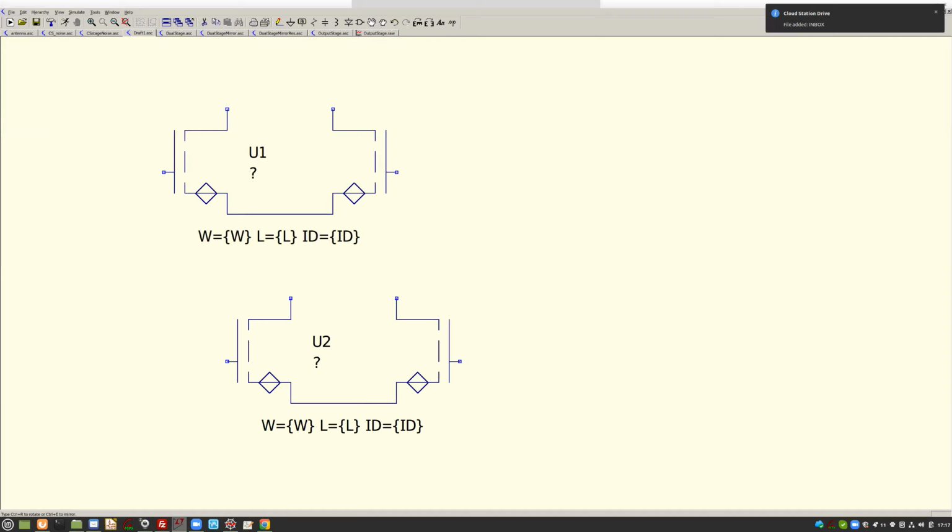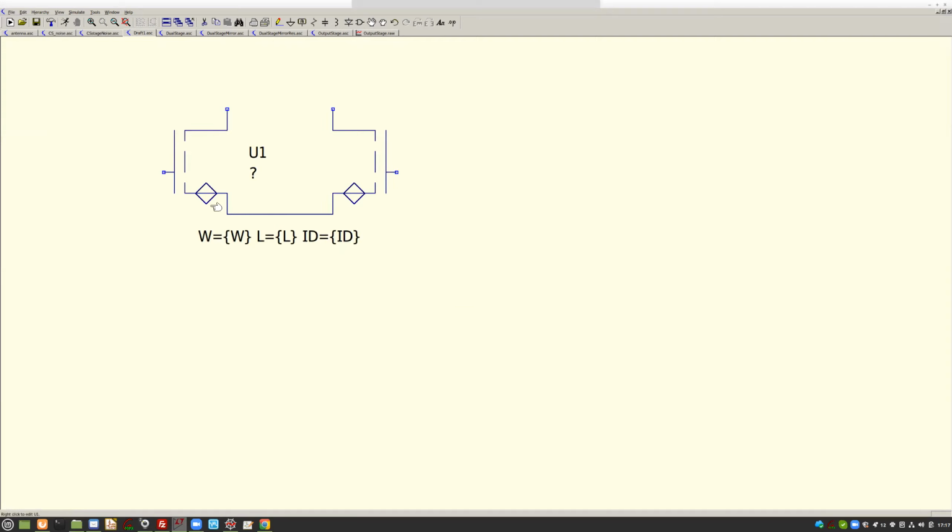The parameters you give are the parameters of the single transistor. So the width, the length, and the drain current are those of the single transistor. And this will be a simple voltage controlled current source with, of course, all the capacitors around it and the output resistance of the stage, but as the completely balanced version, as it has been discussed and described in the book, and as we discussed during the lectures.